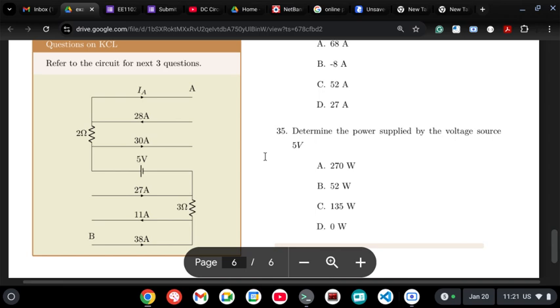Okay. Now from 54, 30 amperes is going towards the right side. So 54 minus 30 is 24. 24 amperes going upwards into 2 ohms, 24 into 2, 48 volts is the drop. Again this is higher voltage and this is lower voltage. So minus 76, again minus 48.